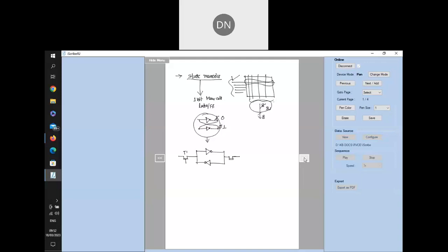Now I'll call this transistor T1, and this transistor T2. This line is the complement line, which we call B bar. This is the uncomplemented line, which I'm calling the B line. These transistor gates are shorted together, and they are called the word line. This word line connects to all the cells present in a given word.